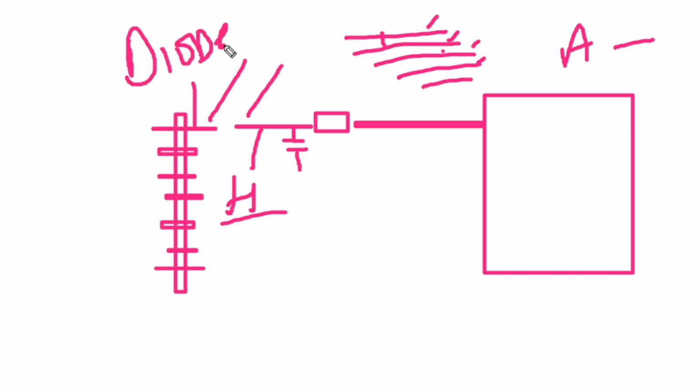Sometimes when this line shorts, it gets hot because it is a very thin line. This high voltage line, this anode line, is a very thin line. Sometimes it connects to the ground. So when you measure on diode mode here, you will see there is a short. I have already faced this type of problem.